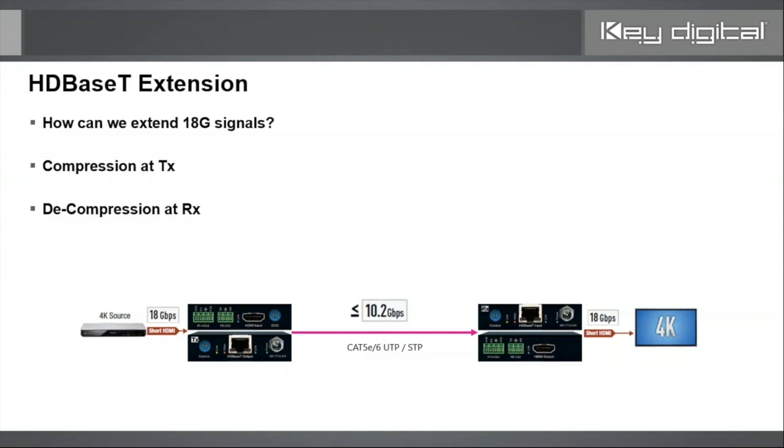And so AV over IP especially has compression applied, and even in the traditional realm of HDBaseT based systems, we're going to be encountering compression. And it's hard to say what exactly will happen, but I think that as new resolutions like 8K are introduced, regardless of their practicality, you're going to be looking at a scenario where that original content that is output on the HDMI must be compressed in order to be sent throughout the professional video, the integrated system there.